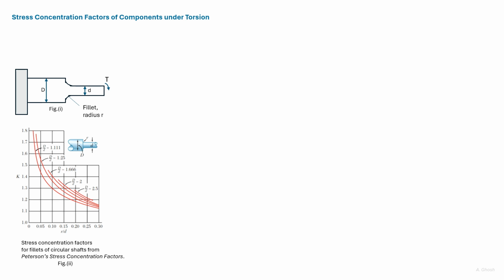We earlier considered a flat plate with a hole subjected to axial loading. The stresses around the hole are higher than the stresses in the rest of the plate. In components with discontinuities, we need to know the higher stresses, since for design and analysis purposes, we use the higher stresses.